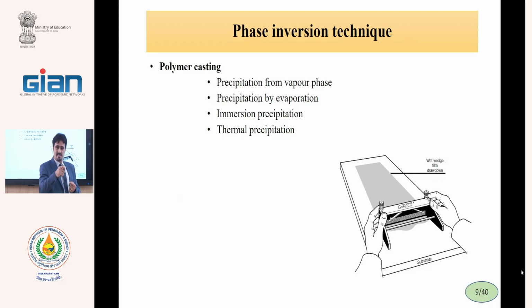And when we add drops of polymer into the non-solvent, it rapidly produces circle particles. We use these methods for changing liquid to solid films, and in this step, with control of conditions, we can produce porous or non-porous membranes. Both porous and non-porous can be produced.